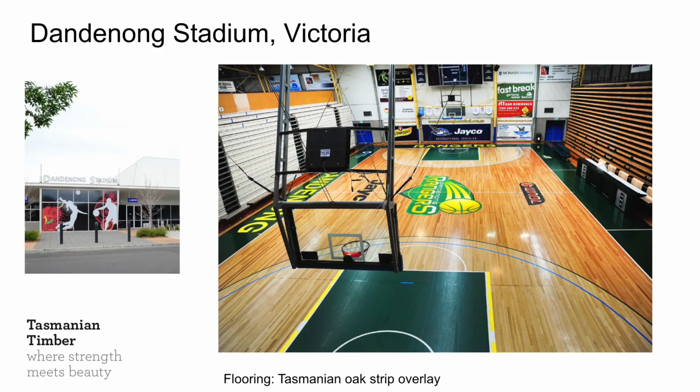The other thing you've got to be careful of with floors, especially big floors like this, is that any change in moisture content means the whole floor is going to change in size a bit. So from a designer, that gives you 2 or 3 things you've got to do. One is you've got to make sure the moisture content doesn't change very much. Second is you've got to make sure that you order the right moisture content to get it into the project. And third, you've got to allow for the fact that some silly bugger is going to get it wet one day. And you need the floor to be able to move a bit, and design it in to do that. And if you don't, someone's going to be unhappy.